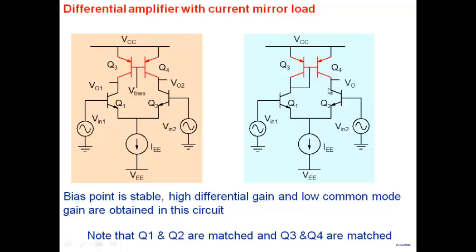This is in IC amplifiers. I would say, if you have a huge number of circuits, and you rank them in terms of their importance, this circuit would rank at the top, the topmost circuit in terms of importance. It's a circuit in almost all IC amplifiers. You'll find a circuit like this in all lines, whether it's a comparator, multiplier, no matter what you think of, you'll find a block like that. A differential pair with a current mirror load. This is an extremely powerful, very versatile, very useful circuit.